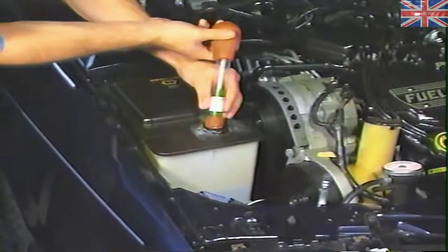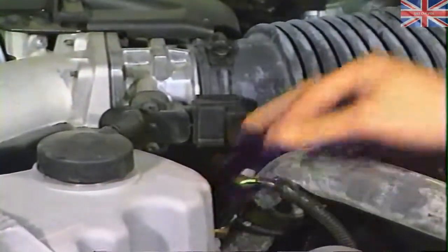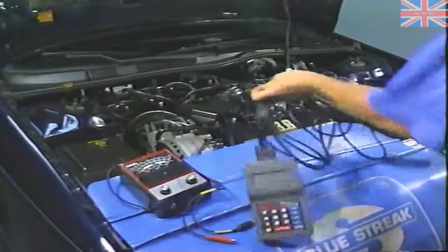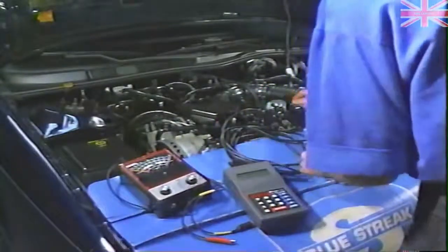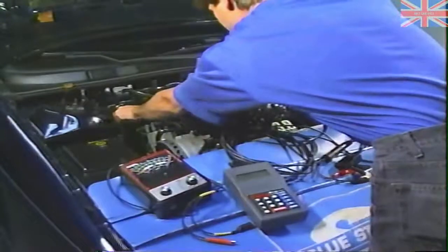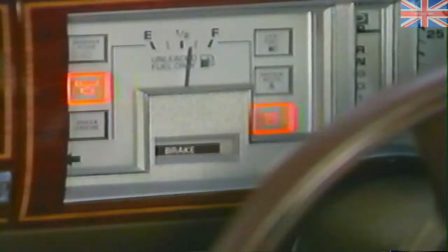Check the operation of the engine's coolant fan and always double-check sensor lead wires and connecting clips. With the necessary information in hand and the visual inspection complete, you need to isolate the system which is causing the problem. This can be accomplished by using either engine analyzers or handheld test equipment. If you are working on a 1988 or newer model, deriving diagnostic codes can be done utilizing the onboard dash